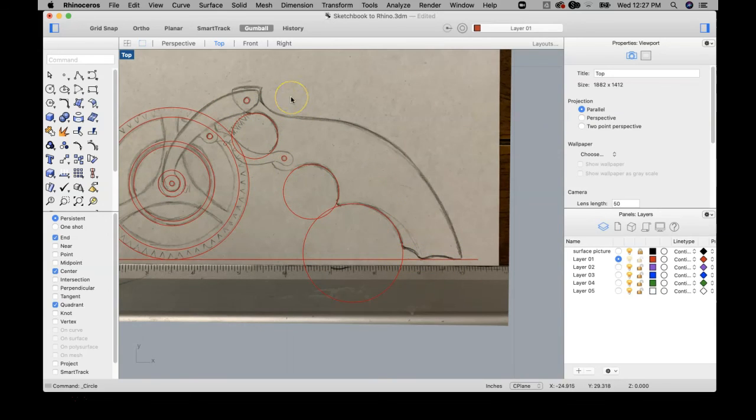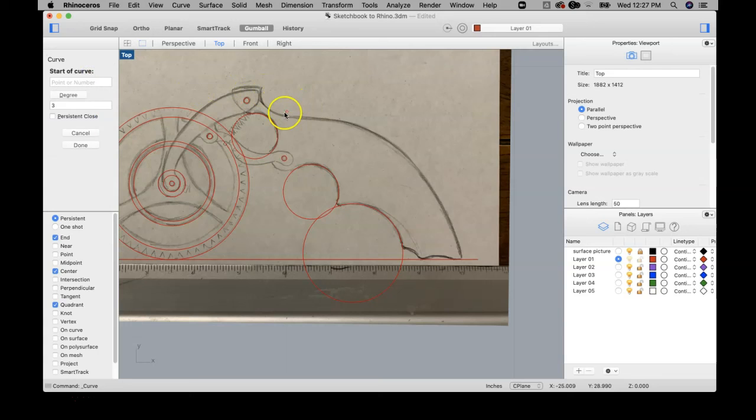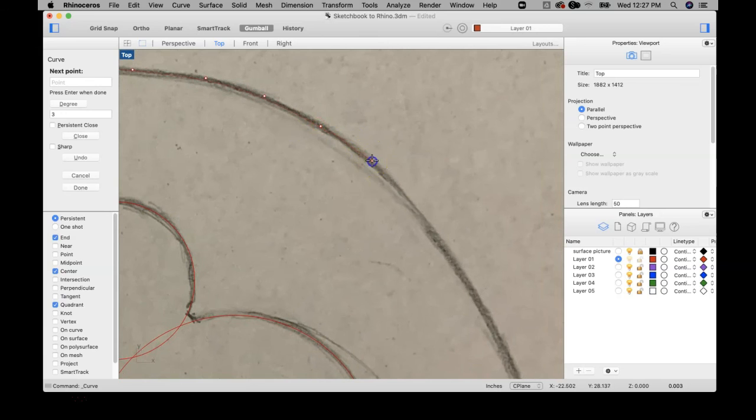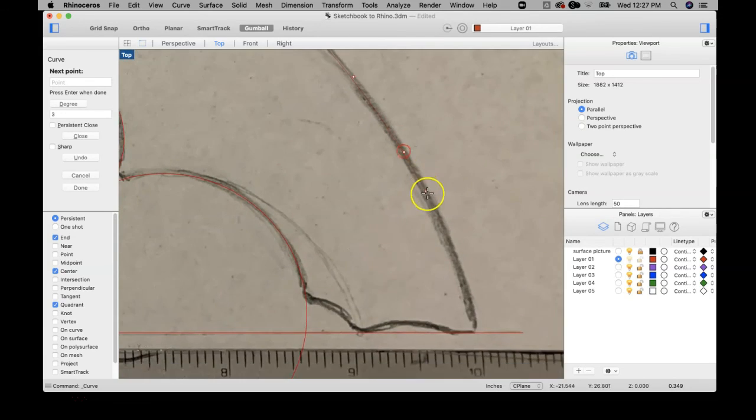Another tool that's very useful in terms of 2D drawing is this icon right here, which says control point curve. I want to demo this. If I've got an existing drawing, I can come in and start drawing. We'll just show you in here in the middle of this. I can draw with this, and you do have to be careful. Rhino builds curves from points, so it's a series of points, and you'll notice how it smooths the line as I'm placing that.